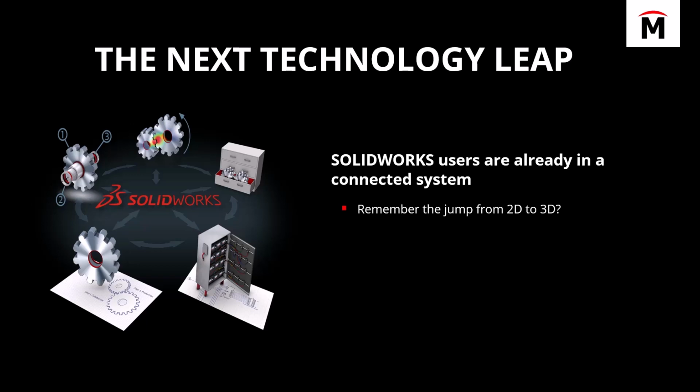So when my part needs a hole drilled in it, that hole shows up everywhere the part exists. Assemblies, drawings, they know it's lighter, they know it uses less material. I only had to put the hole in one place. I didn't have to open up several DWGs and make sure they're all up to date, right? Everything's connected. That was the fundamental jump.